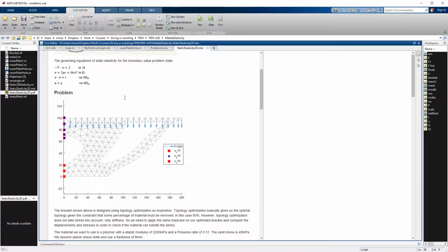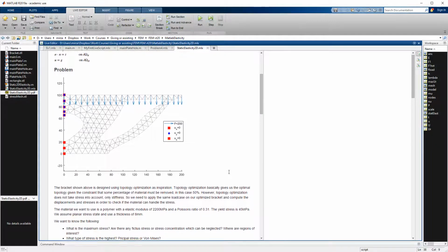Right. So if you watch my previous video tutorial, you will see that this thing has actually been topology optimized using SolidWorks or Fusion 360. And then we drew this on top of our initial design. We drew pockets, which we cut away, and this was the result. Now we want to check if the stresses in here are underneath the yield stress, because the topology optimization does not give us that. So we still have to check the structural mechanics of our design.